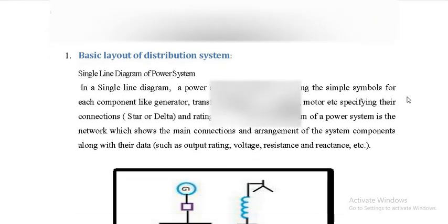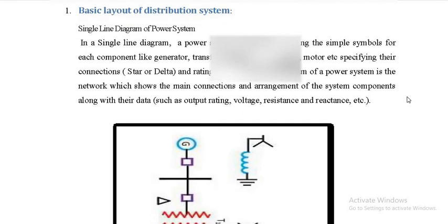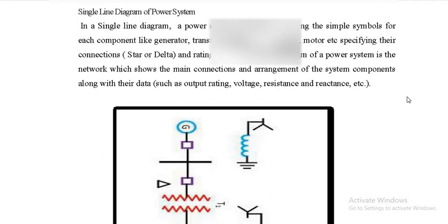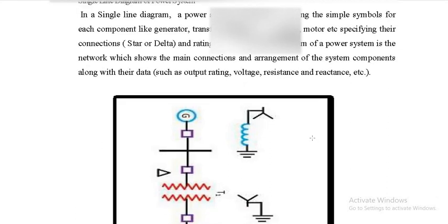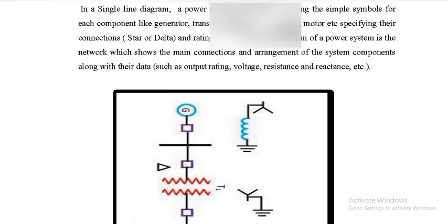When I talk about a power system, you can see this is the single line diagram. The single line diagram, as you can see over here, starts with a generator point. At generation, let us say 11 kV, 22 kV or 33 kV is the generation voltage. When it is transmitted at a higher voltage, you can see a transformer over there, and necessarily it's a step up transformer.